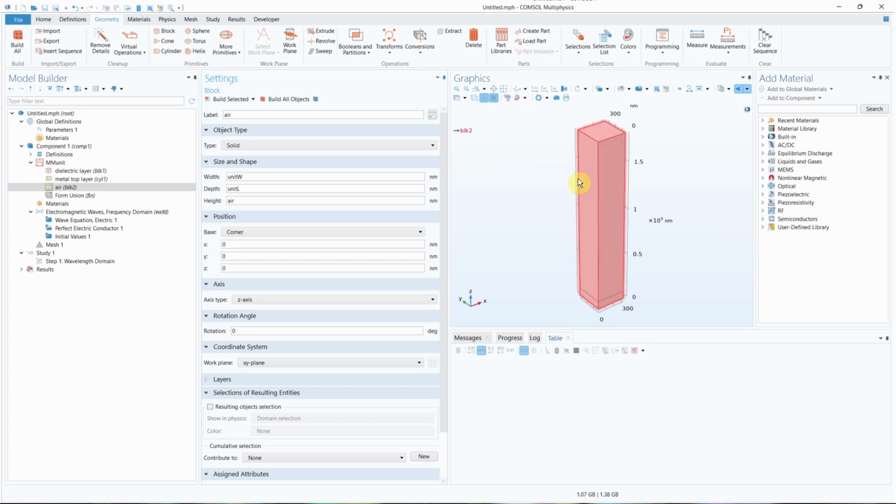It's huge. So this is why setting the air block to some factor of the lambda, or of our target wavelength, is helpful, because we can change pretty dramatically the height of this cylinder. Maybe getting 2 wavelengths away gives us that far field behavior that we want, then it's pretty easy to change that multiplier. But you can imagine if this block is too large relative to that wavelength, then your calculation is just going to take a little bit longer, because the larger the volume, the more calculation points. So making it relative to that lambda helps it scale depending on what wavelength range you are trying to interact with.